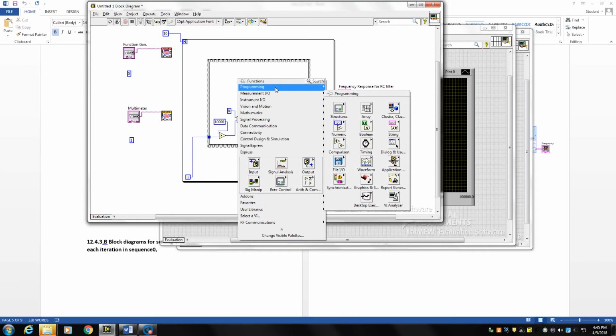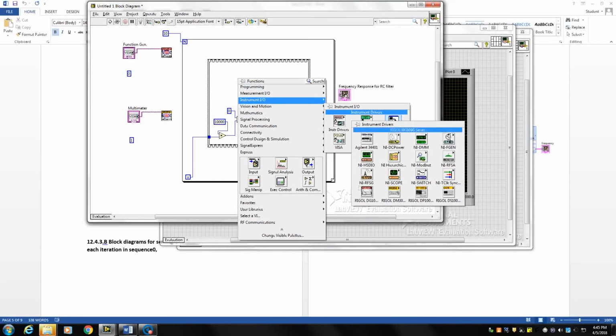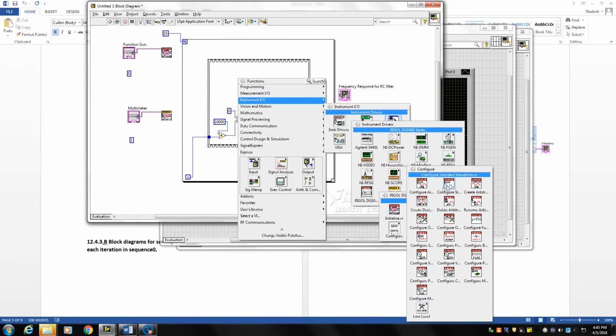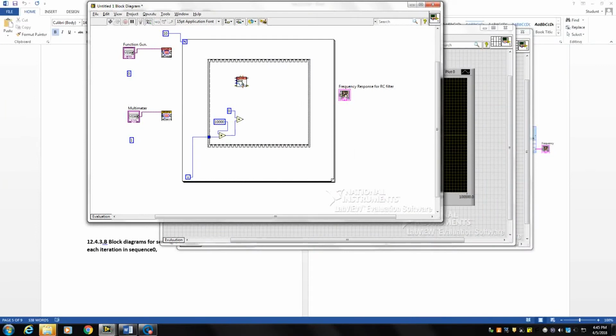As you can see here, the number 2 at the top of this frame indicates that we use the sinusoid waveform. So after this we pass this on and we set the active channel. Actually, we activate the channel, which, as I explained before, is channel 1. We use channel 1 of the function generator.